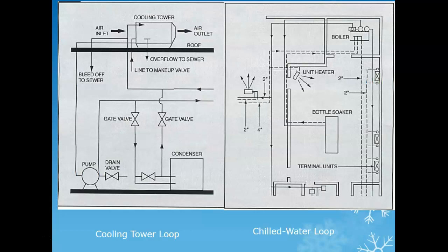I know that because I worked at a car repair place. So most of the time, here's your base component, here's your seal, very, very thin, and here's the secondary component on top of it, okay? What they mean when you've blown a seal is either you've busted one of these, you've got a crack in it where you're just leaking things everywhere, or you've actually torn open all parts of the seal.